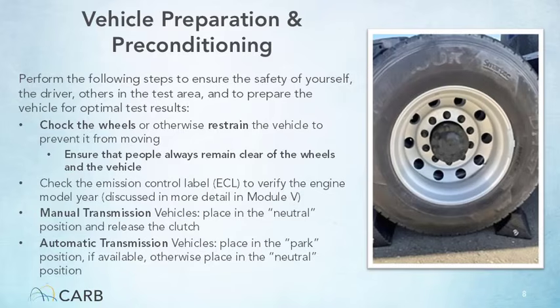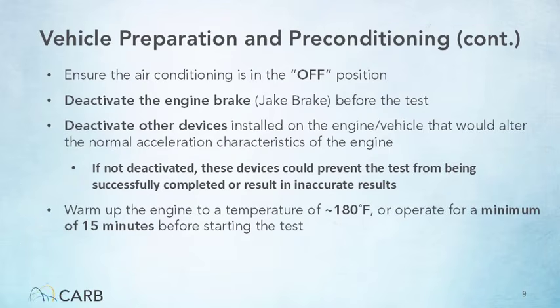Before performing any testing, chalk the wheels or otherwise restrain the vehicle to prevent it from moving and ensure that people always remain clear of the wheels and vehicle. For manual transmission vehicles, place the transmission in the neutral position and release the clutch. For automatic transmission vehicles, place the transmission in the park position if available, otherwise place it in the neutral position. Make sure the vehicle air conditioning is off. Deactivate the engine brake prior to testing the vehicle.